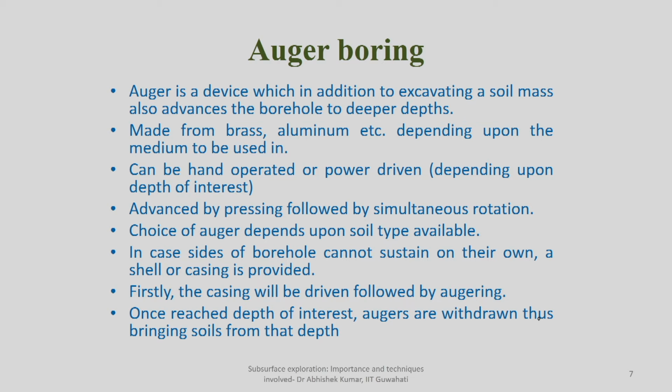But as I mentioned, because the auger collects the soil by means of scratching, whatever soil was there, you are actually disturbing it before it is contained in the auger. So though it gives you what kind of soil is there, it is not giving you any strength property, consolidation property, or index properties, and even the moisture content majority of the time changes. It is only giving you an indication of on an average what kind of soil is there.